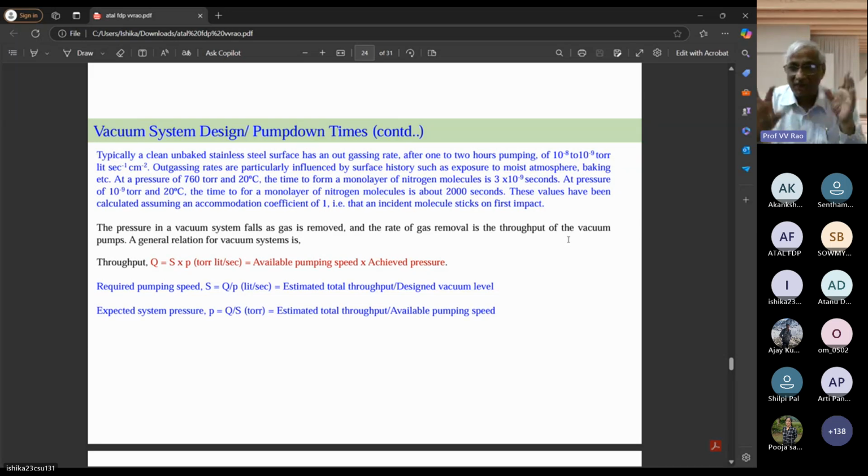All these three disturb the clean ambience, and the residual gas that is formed out of these things is continuously evolving while the pump is continuously removing it. But there is an equilibrium. That equilibrium is called residual gas. That residual gas, you have to analyze using mass spectrometers. If you do that, then you will be able to understand, oh, even if it is bad, that bad thing is only argon. So go ahead, go to the lithography, go to the etching, it doesn't matter, because this argon is not going to make a difference.